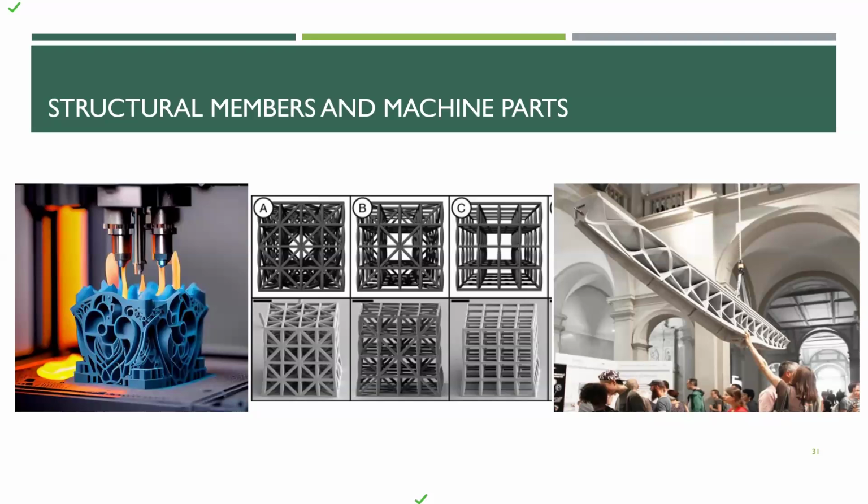If some of you have worked on finite element analysis, you know the critical stress points and how the compression and tension members affect the strength. Instead of whole concrete, we can prepare it in any shape. So this is also an advantage of 3D concrete printing. Instead of preparing the whole solid concrete beam, we can actually prepare a beam like that, not like the conventional beam. This beam can only be prepared using 3D concrete printing, because you cannot prepare a formwork for this kind of beam. And this is a customized structural design for a specific kind of loading.